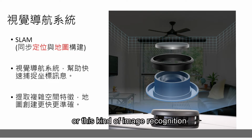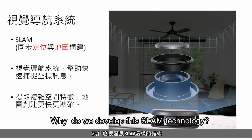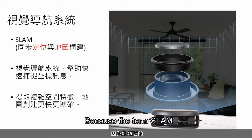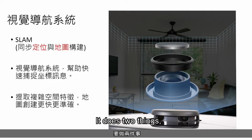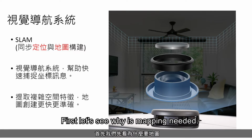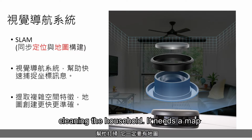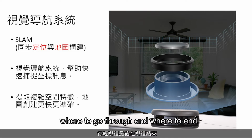Whether LiDAR or this kind of image recognition, it utilizes a technology known as SLAM. Why do we develop this SLAM technology? Because the term SLAM means simultaneous localization and mapping. It does two things. The first thing is localization, and the second thing is mapping. Why does it do these things? First, let's see why mapping is needed. Because it needs to help cleaning the household. It needs a map in order to know from where to start, where to go through, and where to end.